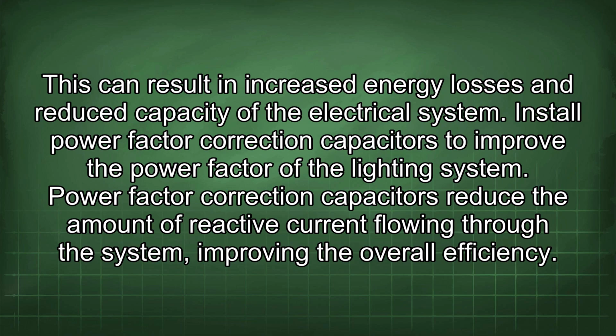Install power factor correction capacitors to improve the power factor of the lighting system. Power factor correction capacitors reduce the amount of reactive current flowing through the system, improving the overall efficiency.